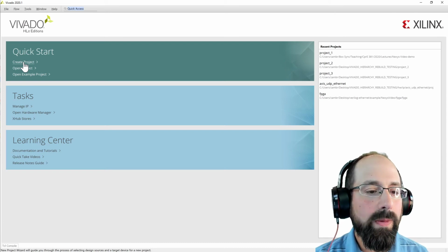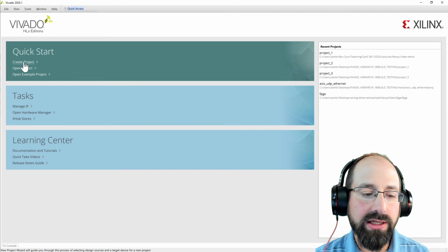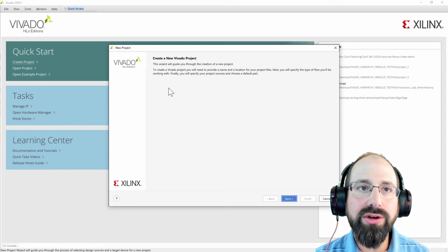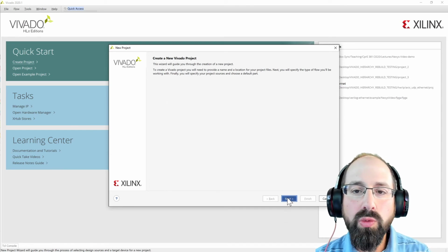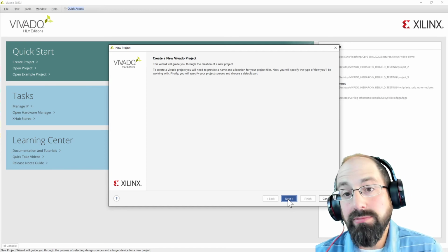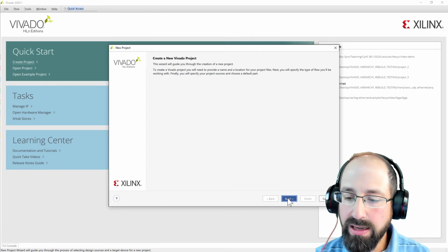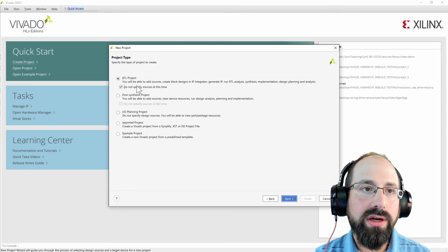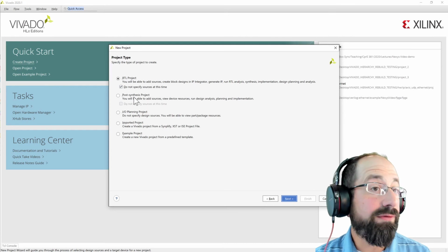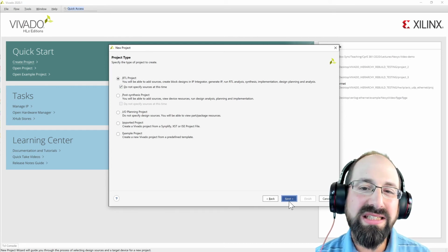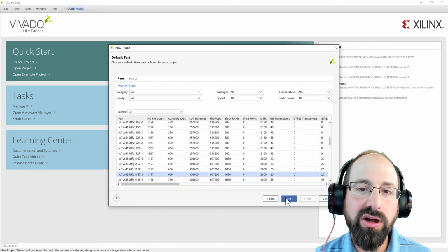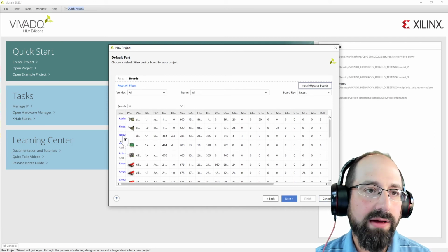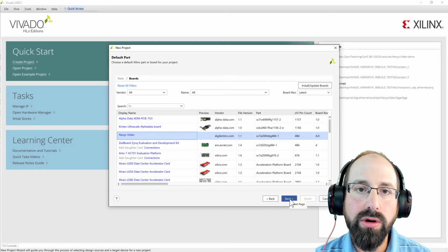So for Vivado, we can very quickly create a project that is targeting that board here. And I'll just walk you through it. Everyone can kind of see that screen. You don't need to know all the really tiny font here. I wouldn't normally use the create a project wizard, but it works for the purposes of what we are doing today. We're going to create just a new project, throw it in that random directory. There's many different types of projects here, but for our purposes, what they would refer to as an RTL project would be a VHDL and Verilog project here. And the nice thing is I've already configured this tool to be aware of the board that I have sitting next to me here. So I'm just going to select that board.